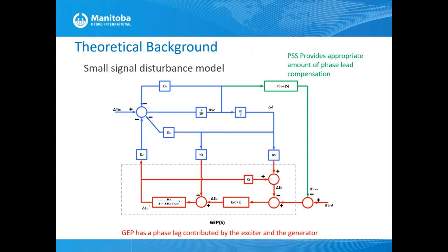If it is in phase with delta delta, we call it synchronizing torque. I think it's hard to compare and contrast these two because they are two different things. But the impact of inertia is to reduce delta omega for the same power mismatch, or the same acceleration torque or acceleration power.